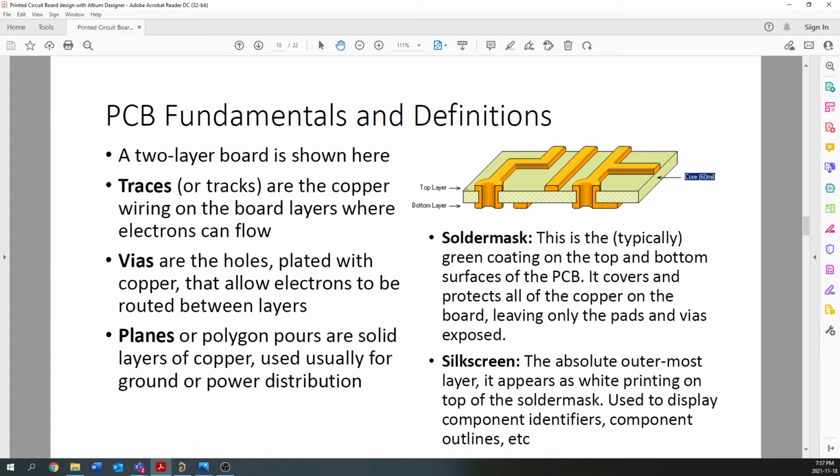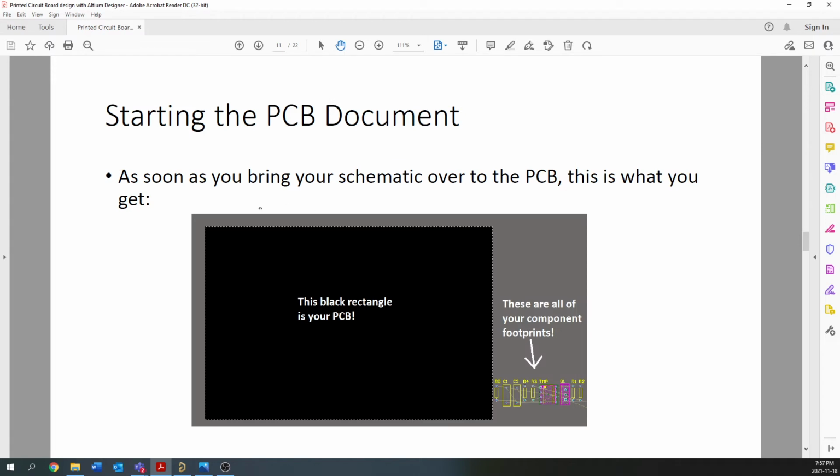So if you drop a coin or some metal touches between 2 components on your printed circuit board, it doesn't automatically short everything out. And solder masks can come in some different colors, and it gets printed over the whole board except the pads and the vias. The silkscreen is what you might see as the white writing on top of the PCB, and that's the topmost layer. So as we just saw, this is what we get.